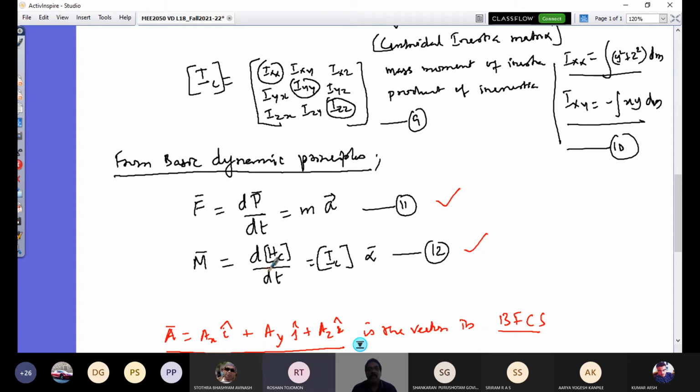Yes, sir. Understood, sir. Thank you. So I require only the first equation when I study an aircraft's motion and I'm interested only in the trajectory the aircraft is flying. Sometimes in the morning in the sky, we see a fog line left and then there is a jet going up. So we look at only the trajectory. If we are interested only in the trajectory, you can treat your aircraft as a tiny point in the sky. At that time, do not look at the physical geometry. So the first equation alone is sufficient to describe its translatory motion in space.